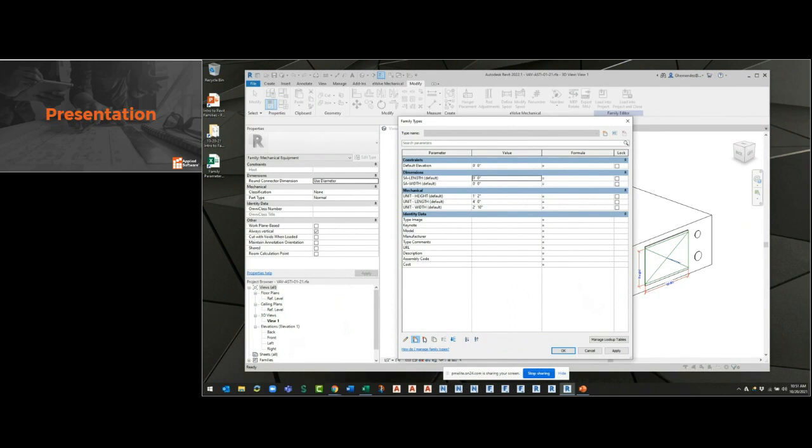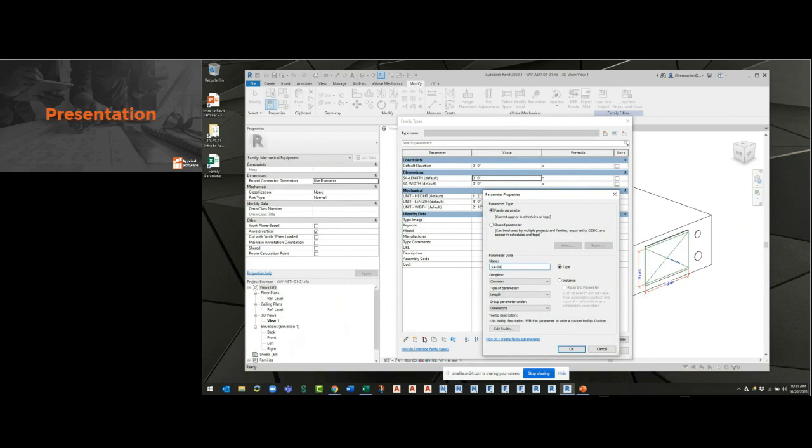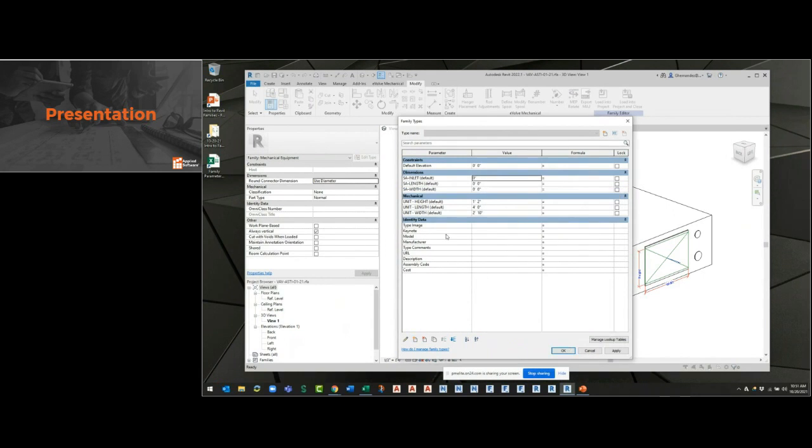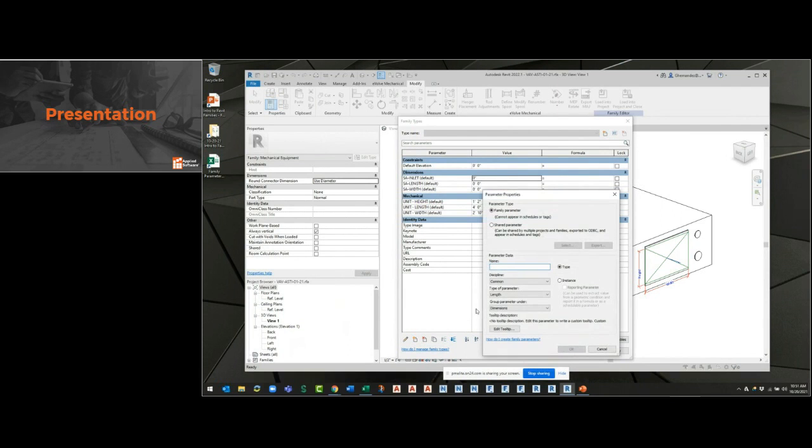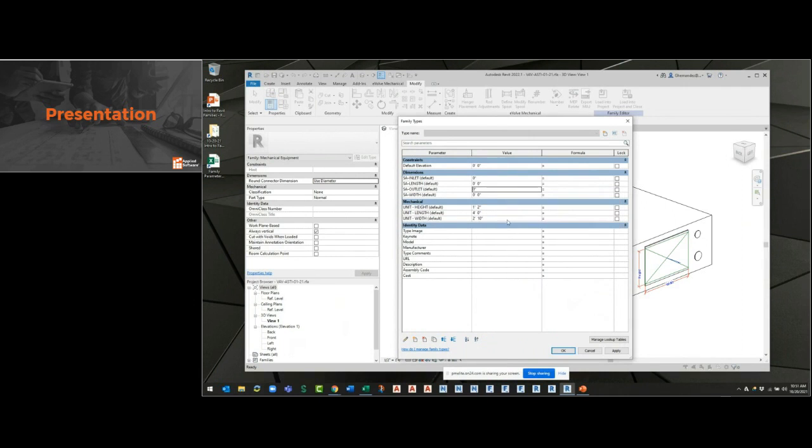And then I'm going to do a supply air inlet, instance. This time I'm going to use HVAC, and then I can use this one called duct size. So you'll see the difference between a length and a duct size when we're actually doing this for duct. Outlet, discipline, HVAC, duct size. Click on OK. So now I've got my dimensions here for my inlet, length, outlet, width.